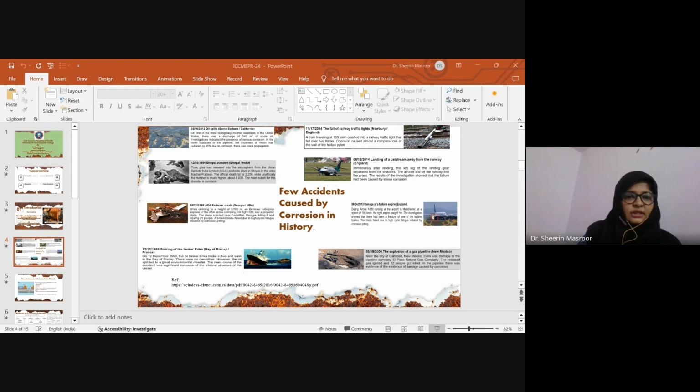There are different methods applied to protect our metallic structures: design improvement, change of metal, change of environment, and potential change. Change of environment is further divided into removal of corrosive constituents, application of corrosion inhibitors, and change of operative parameters. Next comes coating. Coatings are divided into inorganic coating and organic coating, depending on the material background from which they come.